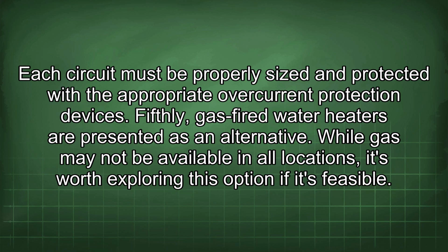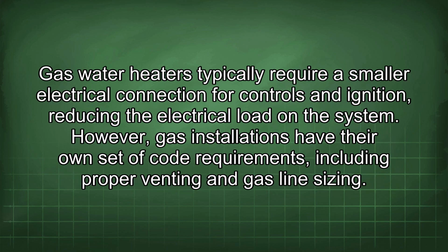Fifthly, gas-fired water heaters are presented as an alternative. While gas may not be available in all locations, it's worth exploring this option if it's feasible. Gas water heaters typically require a smaller electrical connection for controls and ignition, reducing the electrical load in the system. However, gas installations have their own set of code requirements, including proper venting and gas line sizing.